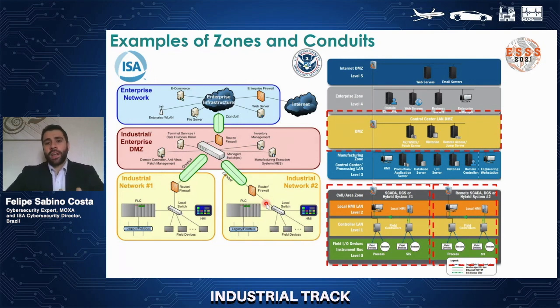Once you have defined the defenses on the products, I'll also create layers on your network, because a huge problem that industrial control systems have nowadays is what we call flat networks. That is just the first layer, like we mentioned: the segregation between the corporate enterprise network and the industrial control system usually doesn't have any other barrier.